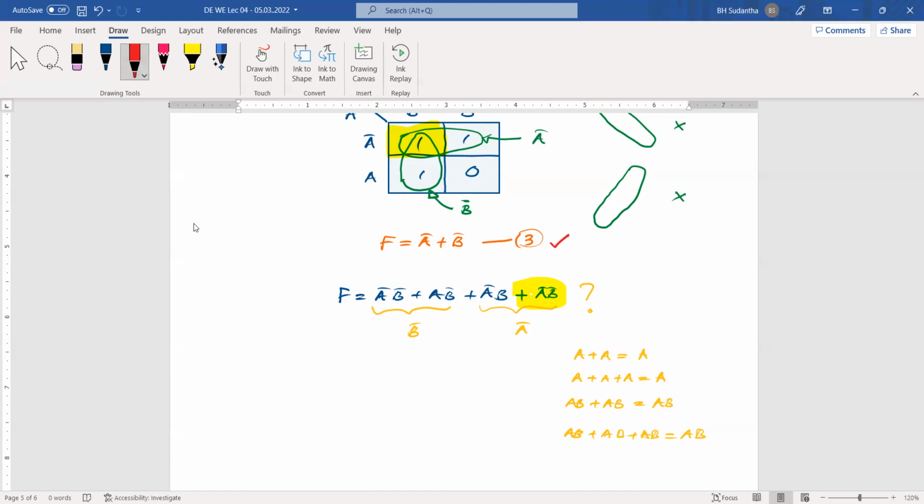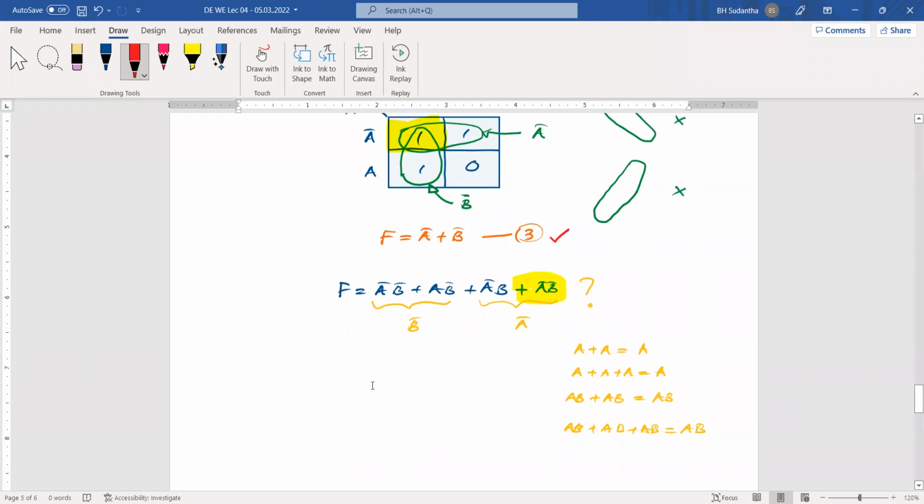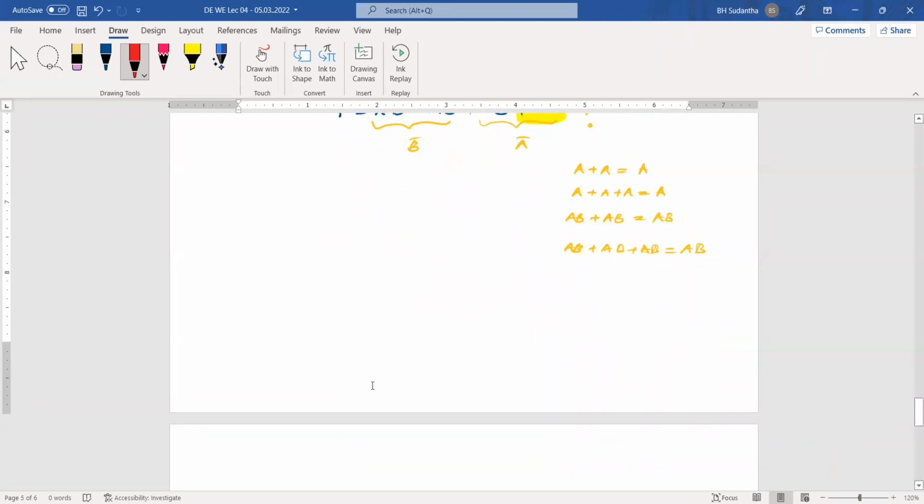Then here, we are learning the first rule of Karnaugh maps. What is the first rule? One grid can be covered many times if it helps minimization. Remember that. It is not a must. It is not necessary to cover one term many times all the time. But if you see that it helps minimization, then you can take it. Otherwise, it is not necessary. Okay, we will have a couple of examples later on, then you will realize this. For the moment, we can take it like that. It's okay.